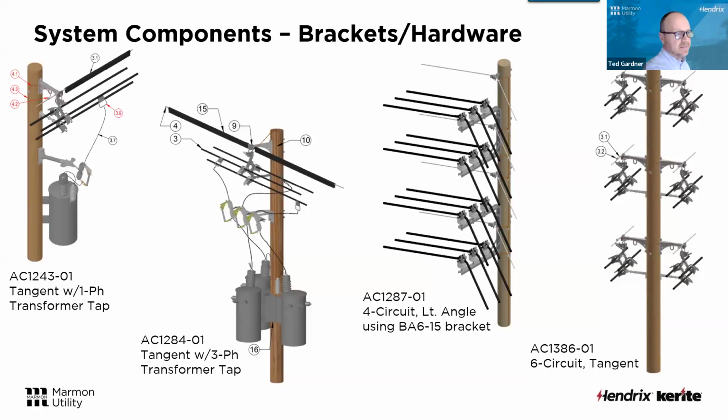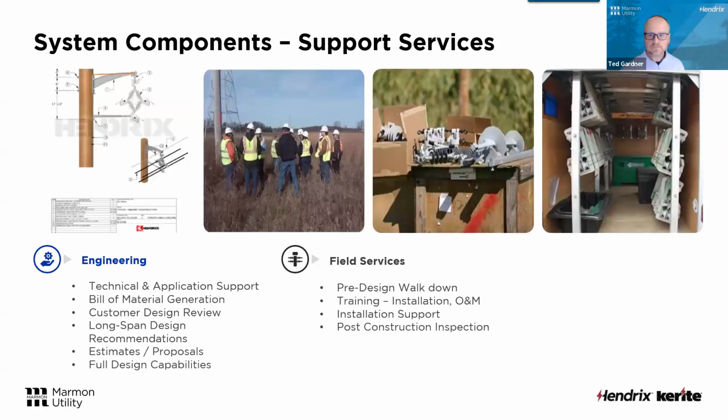But you could take that same messenger where that's attached and leave that alone, take that spacer out and hang a crossarm. Spread those phases out horizontally on a crossarm with just a set of pins and insulators, and then you could open up the covering and make your taps right in a row for your three-phase bank or your three-phase switch or whatever you've got, just like you normally would. So again, quite a bit of flexibility when it comes to the arrangement of the phase conductors.